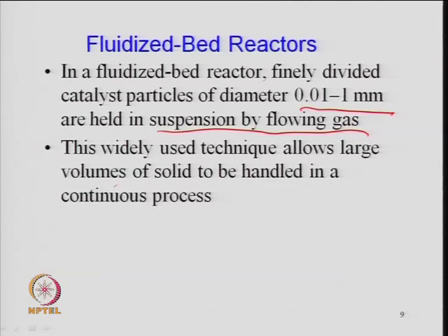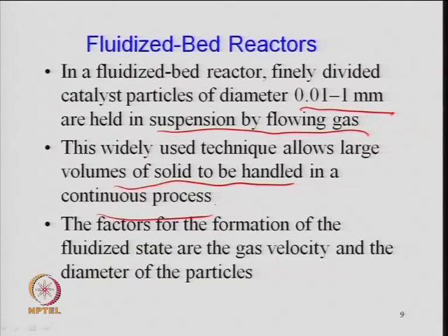because it allows a large volume of solids to be handled in a continuous process. One can handle a large amount of catalyst, and there is good contact between the gas and the solid. The factors for the formation of the fluidized state are the gas velocity and the diameter of the particle. There are several other factors also, but as I said, it will depend on the density of the gas, the density of the solid, and the viscosity of the media. So, there are many other factors also.